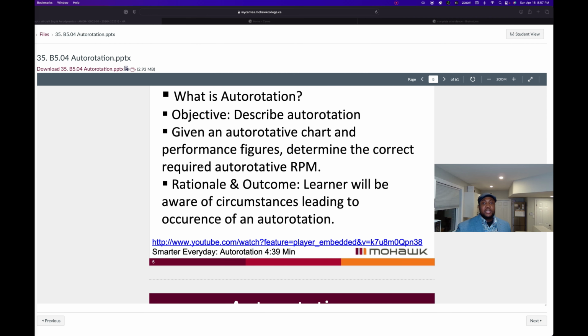The next factor is gross weight, or rotor RPM. The helicopter's gross weight is an important factor in how it will perform during autorotation. The higher the weight, the lower the desired descent rate. So if you have a very heavy helicopter, you will actually be looking for a very low descent rate. A higher gross weight during descent would tend to cause the rotor to accelerate too much, possibly causing overspeed of the rotor. The collective is adjusted to increase blade angle to maintain proper RPM during descent.